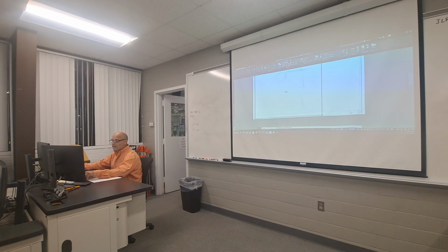Here's something else that I'm going to need you to do for that border and title block. On yours, you do not have all the scales set up. So when you open up AutoCAD, and y'all can just take notes and write this down, you've got a lot of scales down here, but remember, these are all architectural scales. They all end with equals 1 foot dash 0 inches.